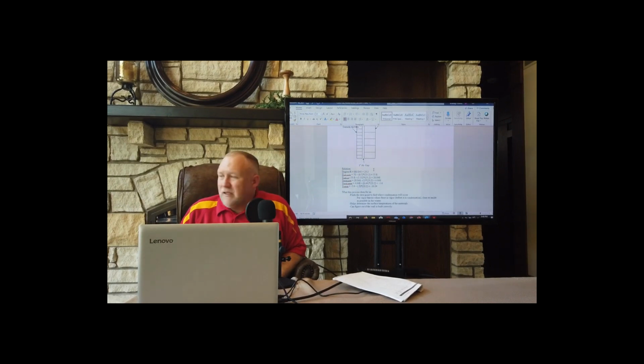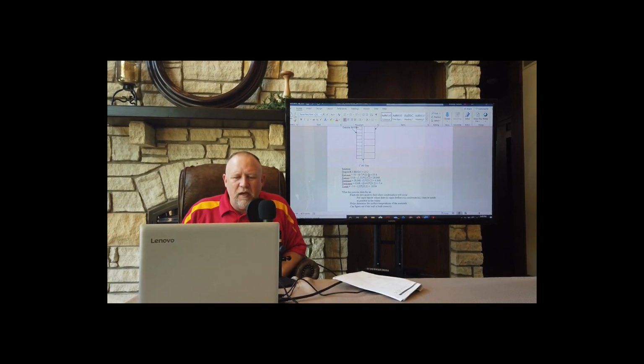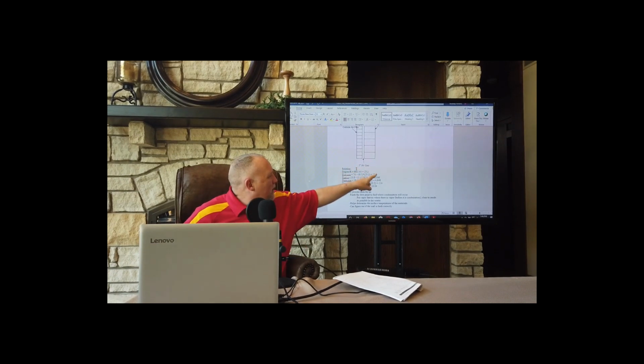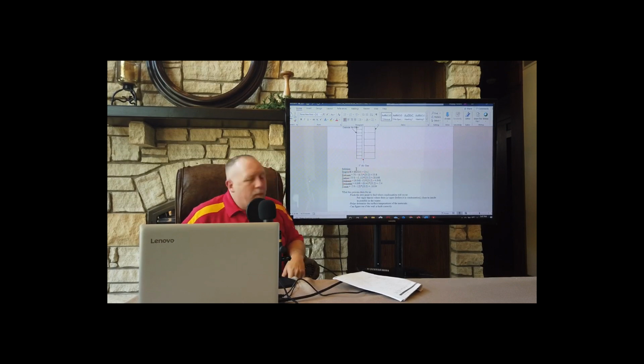Next, we're going to do exactly the same thing. We're going to keep going from inside to outside. So at the wall, it's 53.8 degrees. If I want to find out what the temperature is at the block, I start at 53.8, that's the temperature we just found, minus 1.11, that's the R value of the block, times 23.2, and that gets us to 28.048.